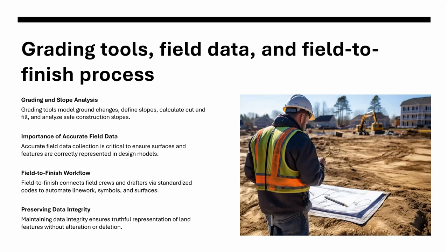These are not just engineering exercises. They matter to surveyors and drafters because they affect how land can be used. For example, if your grading misrepresents slopes, a site might appear suitable for building when it is not. If your contours suggest drainage flows away from a building when in fact it flows towards it, you've created a dangerous misrepresentation of the land. Surveying and drafting are not only about describing the land as it is. Sometimes they're about modeling the land as it will be. Either way, accuracy and fidelity matter.